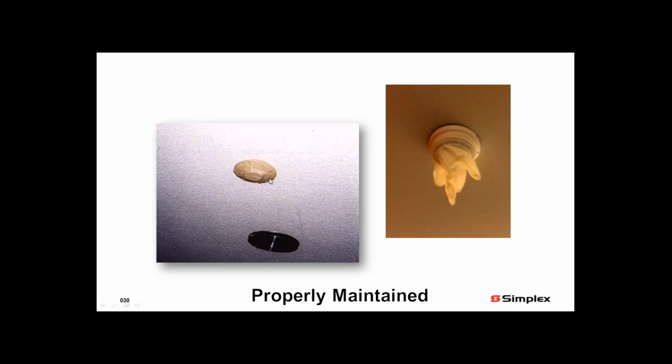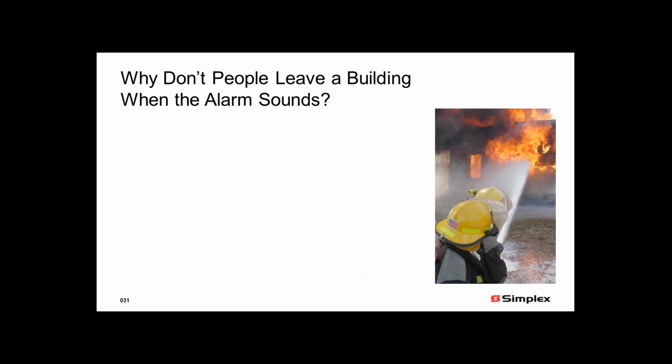Well, nobody bothered to go in and take the tape off, much less the person that was doing the inspection year after year, who didn't notice that it was full of tape, so the device wasn't even being tested properly. And then a picture on the right, Peter found this one, where somebody took a rubber glove and stuck it over top of a smoke detector. Not the exact best way to protect the device, but somebody did that. And then obviously left it like that, and there's no way that smoke's going to penetrate into that chamber to alert us that we have a situation developing.